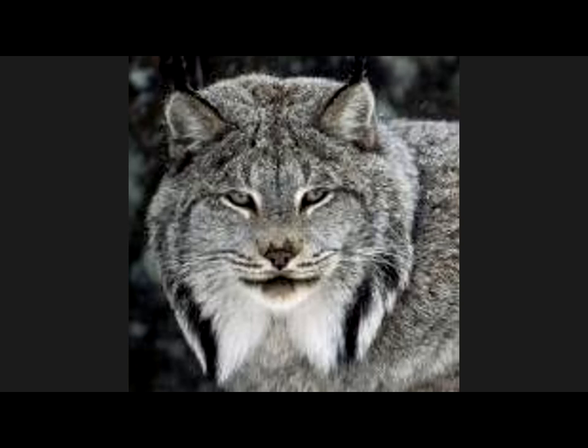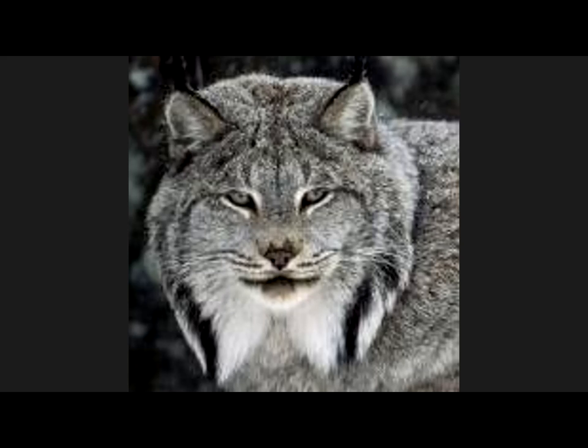So there's a DAC in every pin, and then there's a streamer for every cog, right? Yes. The way it works is the cog is feeding the streamer from its LUT, and the streamer is then connecting those to the DAC channels into the smart pins. So it goes cog, LUT memory, into the streamer, out of the streamer, into the smart pin, the 4 smart pins that were designated as the DAC channel receivers for that particular cog. Then the smart pin does the actual DAC output.